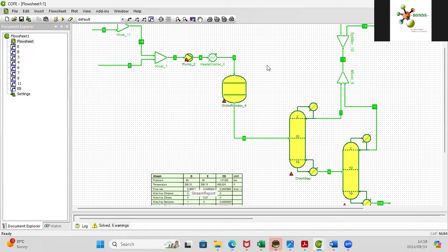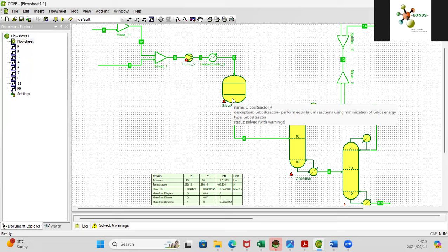Sometimes it will look exactly like what you have here, a couple of mixers there and there, a pump and whatever. However, the process flow diagram should approximate what your process would look like in reality. So if it's going to have 3 pumps, you're going to put in 3 pumps. Not backup pumps, but if it's going to have 3 pumps, that will change the conditions of your process streams, right? If, for example, in your reactor, you're going to have a pump around stream, if that affects your mass balance, it should be here.